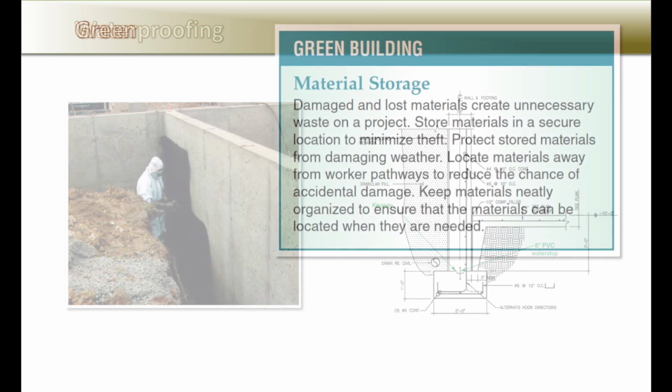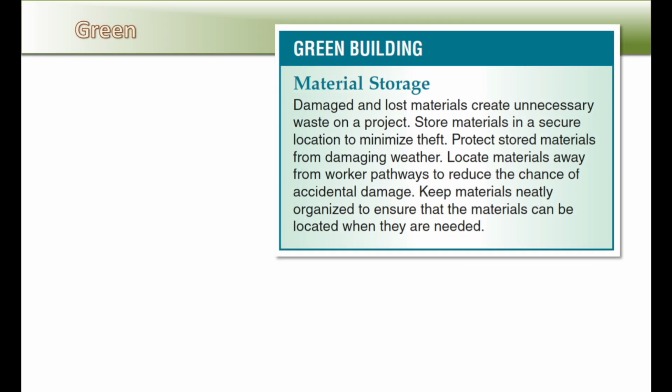Being green as it relates to storage. Damage and lost materials create unnecessary waste on a project. Store materials in a secure location to minimize theft. Protect stored materials from damaging weather. Locate materials away from worker pathways to reduce the chance of accidental damage. Keep materials neatly organized to ensure that the materials can be located when they are needed.